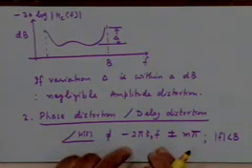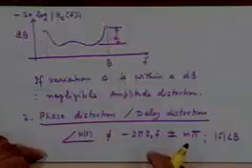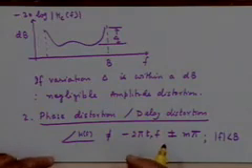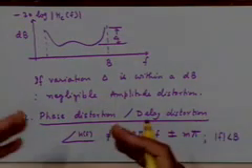If this is so, what is the amount of delay introduced at frequency f? T naught, right, and it's the same for all frequencies, right. If this is not so, basically what it implies is that different frequency components undergo different amounts of delay, and that's why when they combine together all these frequency components at the other end, at the output, the signal does not appear to be the same as it started with, right.